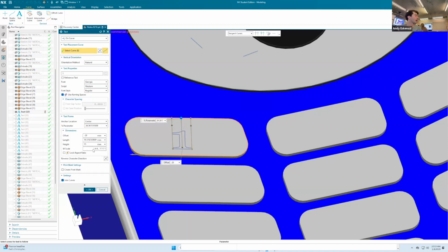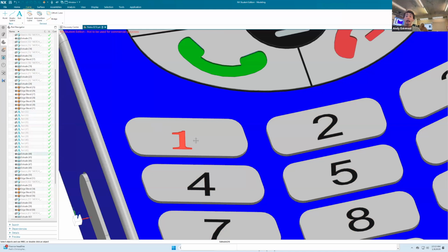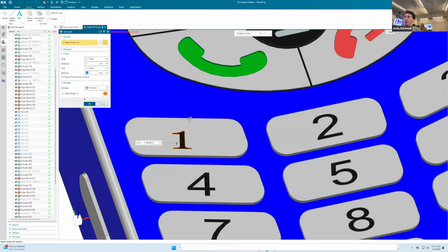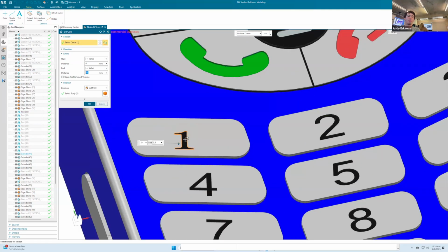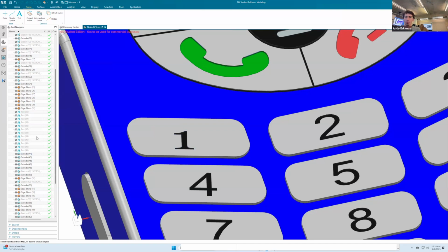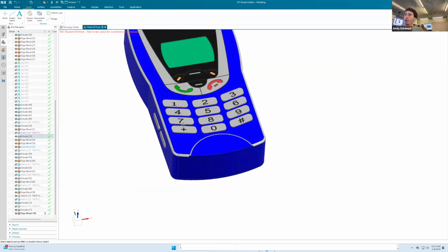Yeah, so you can specify a couple more parameters on how big you want the number. Normally in other softwares, the text is part of the sketch. Here in Onshape, in Siemens, it's an exterior thing. So once you have your text written down, and actually I did modify it, now everything updates properly. I just did one extrude, and that extrude was specific to number 1 in there. So you can extrude as you go. And then the remaining parts are just adding a couple more details.